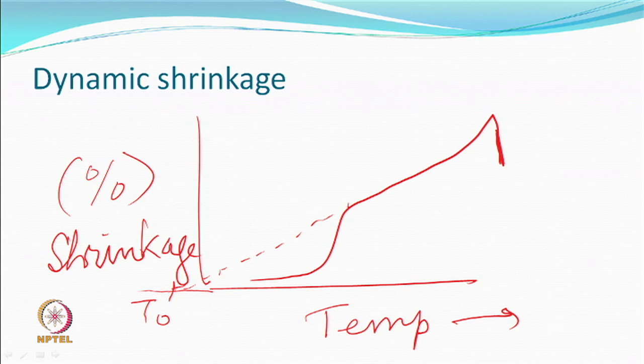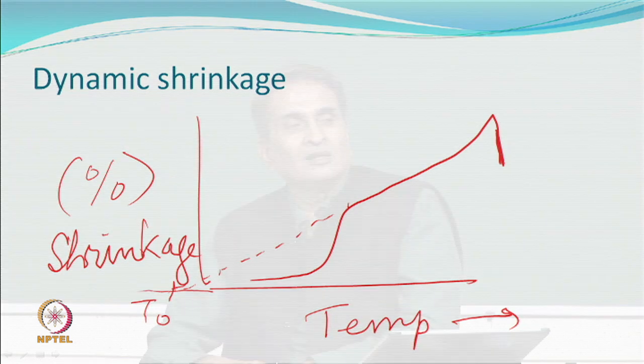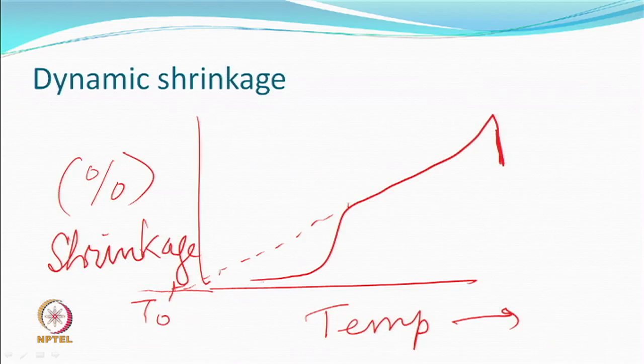So, you have a fiber which is hanging in a solvent at a certain weight, you are measuring shrinkage. So, start from a lower temperature. You find that the shrinkage is not very high to begin with. At a certain temperature, suddenly shrinkage starts. After a certain temperature, the curve becomes slow, which means for that temperature equilibrium shrinkage is approximately coming. So, here this temperature is rising, like you have a DSC, you see a rate of heating, you can set up the rate of heating.